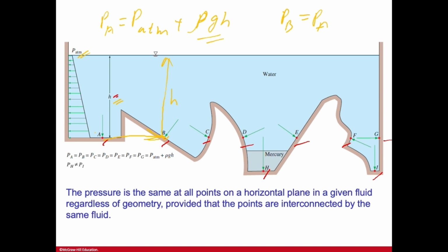And the force acting on the surface because of the pressure at that point acts normal to it. So if you have an inclined face like this, you'll have a pressure acting here. Now if you look at the pressure at C, it is at the same height or depth, so you'll have the same pressure. Same thing with points D, E, F, G. Now if I create another point, let's say Z, first of all, which direction will the force on this surface act? It will act normal to it.